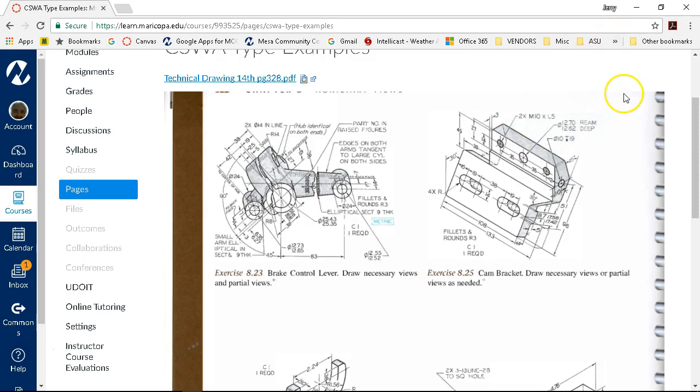So picking an origin. We're not really being given origins here, but I'm just going to go with the lower left, just as a convenient spot to draw everything out some distance at a 30-degree angle, and pick that up. The reason that I'm doing that is because it's probably going to be a lot less painful to draw it in the orientation of the isometric than it will be to try to draw it flat and transpose all of those numbers. All right, keeping it in that orientation.